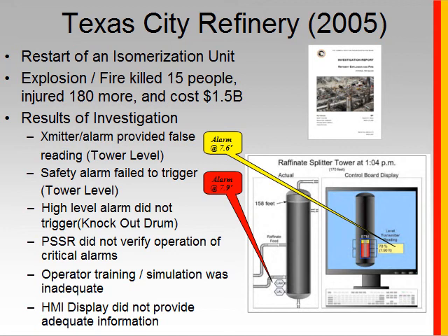Now, some of these, particularly the safety alarm for the tower, had been identified as needing maintenance, and there had been some problems associated with that. Unfortunately, before the startup of that unit, the pre-safety review, those devices were not checked. Those alarms that were critical to the safe operation of the unit were not checked to make sure they were working.